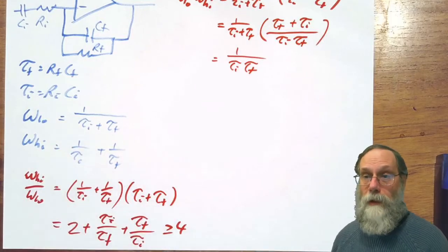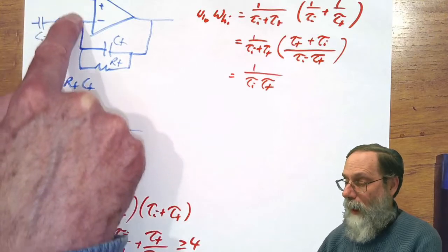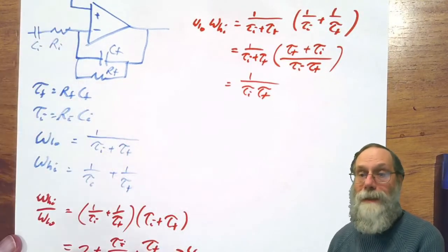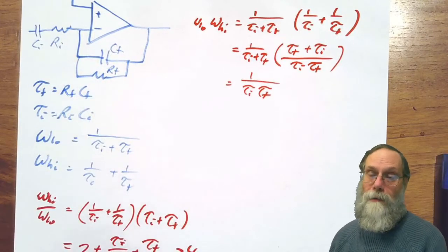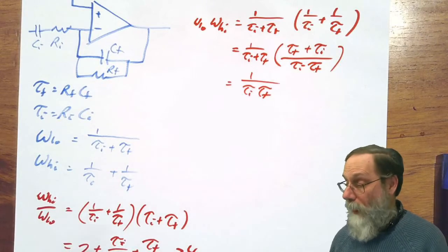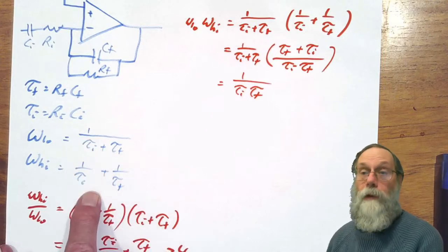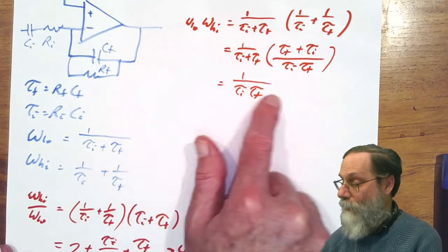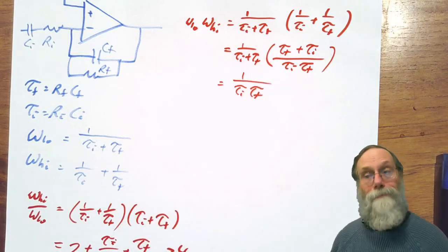And this is an approximation that people often use when designing that. They just say, okay, I'll put my low corner frequency on this impedance, and I'll put my high corner frequency on this impedance, and I'm done. And that works pretty well if the corner frequencies are far apart, because you can approximate this thing very closely with that. The center is going to be in the right place. Everything's going to work just fine.